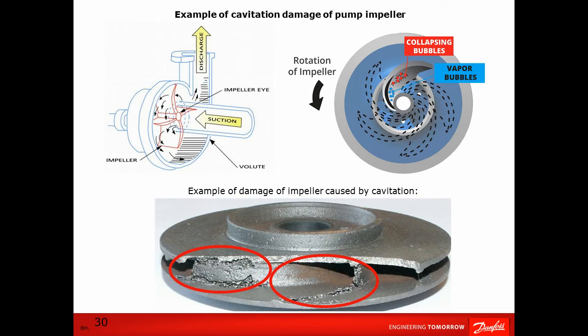The picture to the right shows a typical cavitation. Cavitation typically occurs in the low pressure zones, and gas bubbles will be pushed towards the periphery of the impeller, towards the high pressure zone. In some places, along the surface of the impeller, the surrounding pressure will be so high that the gas bubbles collapse. This is where the material erosion occurs.